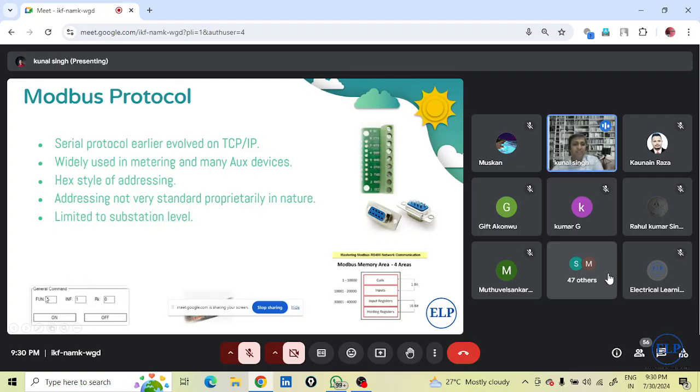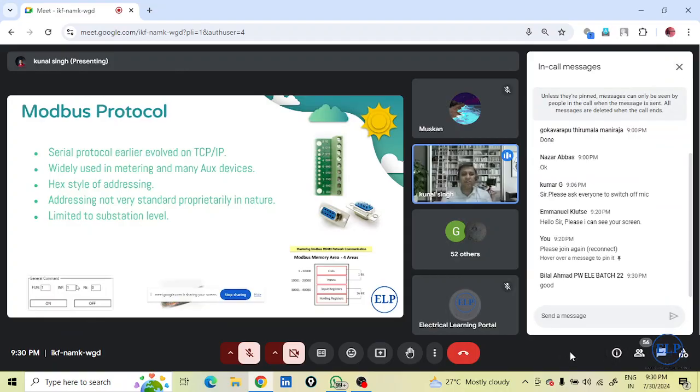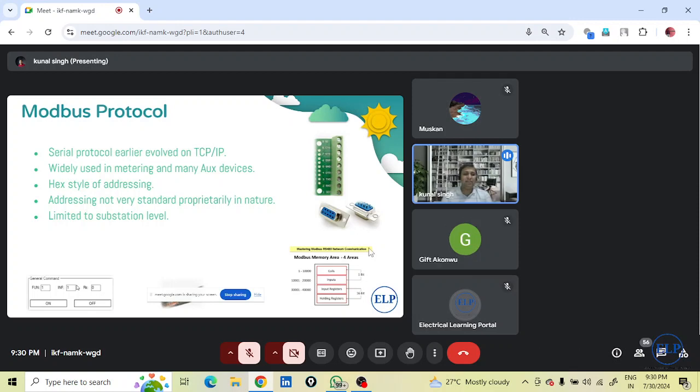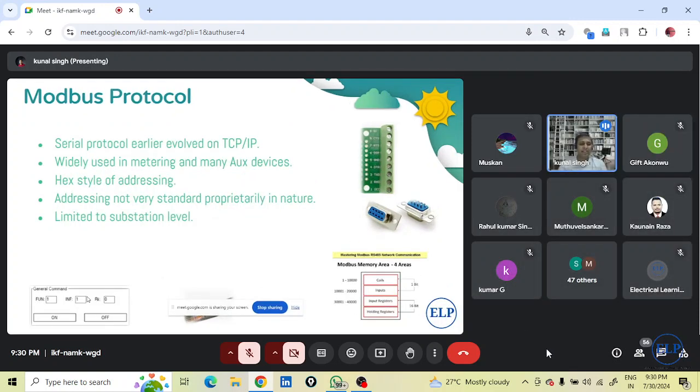This function type and info number for the same data, like I am talking about overcurrent protection. It's a very simple protection used in most relays. For overcurrent protection, there may be an address associated with it, which will be sent to the RTU or remote control center. But the address for a Siemens relay may be 11. For ABB, it may be 1000, 10,000. For Schneider, it may be 5,000, 2,000. And also, it's a numeric value. So you cannot understand that it is an overcurrent element.